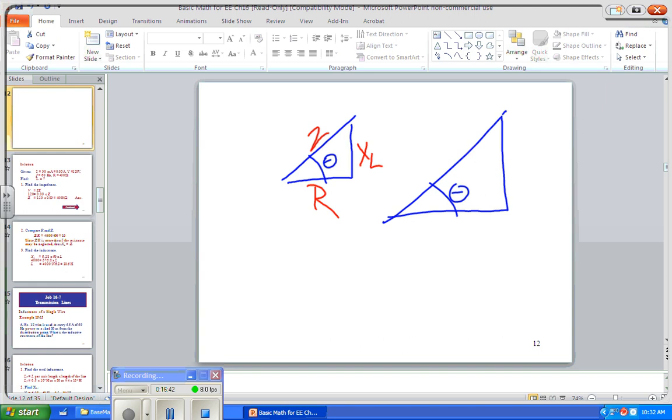And if we take that over to a power triangle, and let's say we're multiplying up to find our total power, that's apparent power. We can find our apparent power, and apparent power always goes up here. And apparent power is always measured in VAs, volt amps, because the voltage times the current is the apparent power. So VAs, volts times amps, apparent power is VAs. Okay, it's nice and simple. Now, the true power is actual wattage, the actual cranking force or the actual work being done by a circuit.